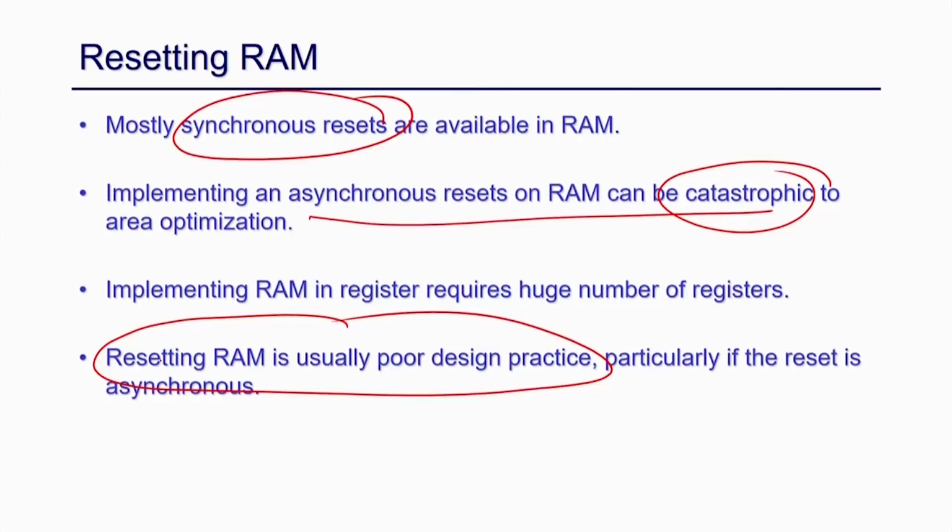So, in general, resetting a RAM is a poor design practice. You usually should not reset a RAM. That has a very bad impact on FPGA design, specifically if your reset is asynchronous, because in that case the RAM will map to a huge number of registers.